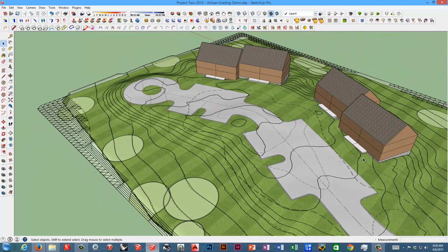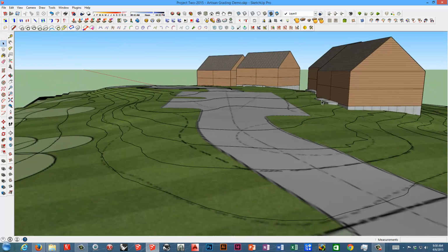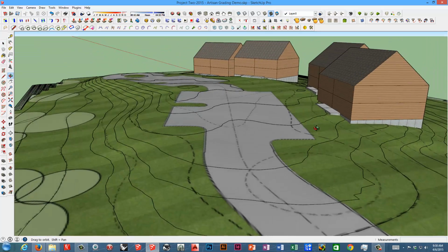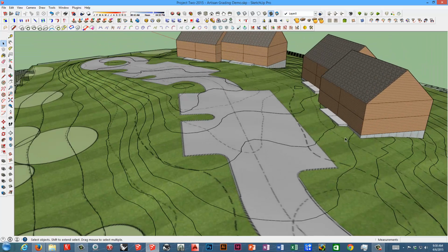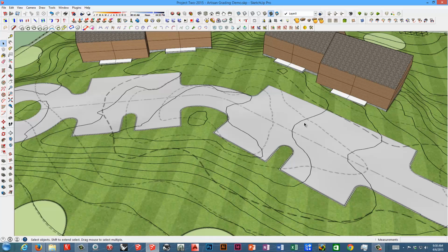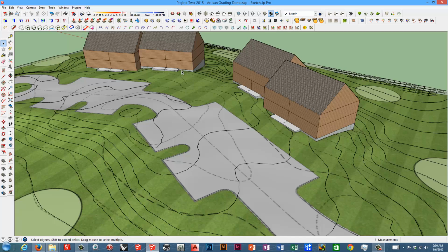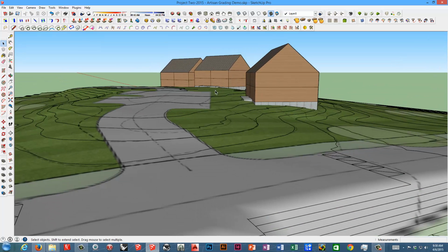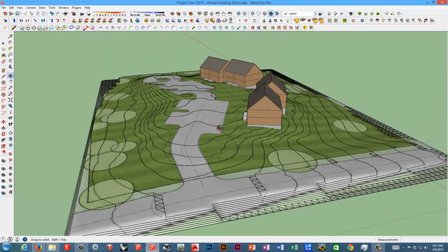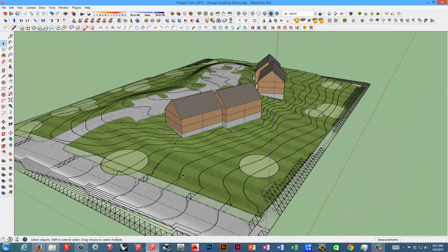Again, down here at this edge, I've got a couple options. I could decide, well, maybe I'll pull this building up a little higher, or these contours essentially bend around and hit into the building to create a little swale at this end here. Same with this. This could come in and turn around to create a swale through here, past the sidewalk. So this would indicate to me that maybe I need to set these buildings a little higher because I really want positive drainage coming off of these all the way down. And right now, coming off of this, it's actually draining down to here, and I want that to come back up.